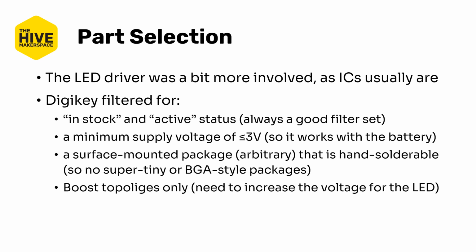And lastly, I chose boost topologies only because I had a 3-volt battery and I needed to increase the voltage up sufficiently to actually drive 4 LEDs, since each LED drops roughly 2 to 3 volts. So I would need at least between 8 and 12 volts at the output to actually drive those LEDs successfully, which is what boosting is. This resulted in 26 options.